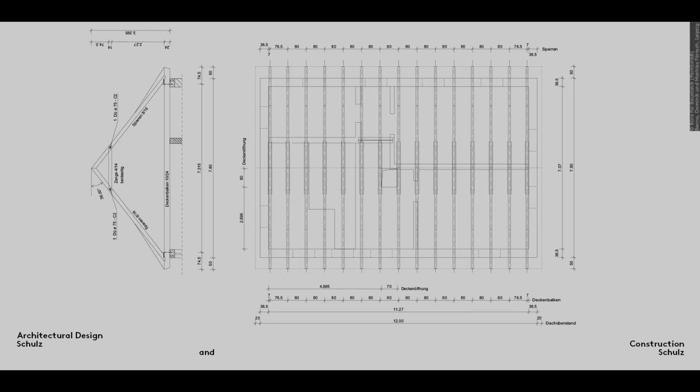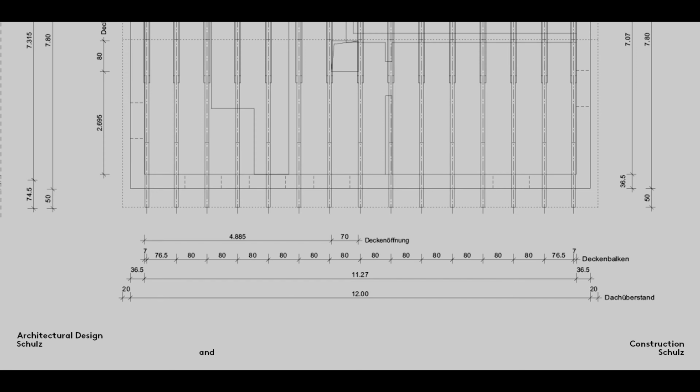Here you can see a simple collar beam roof in both plan view and section. Once again, the drawing is far from perfect. Though the plan view of the floor beneath the roof shows all the important elements, it is not split into two planes showing joists and rafters. The dimensioning, however, which shows all key measurements and references to the masonry structure, is exemplary. The dimensions also show how center distances can be manipulated when the joist arrangement does not quite work out.